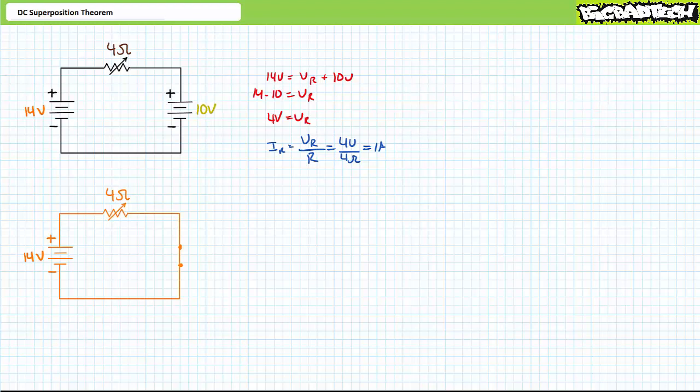Remove the deeply discharged battery from consideration by replacing it with a short. The charger would force current in the clockwise direction, and the current controlling resistor would experience the full 14-volt differential. An application of Ohm's law demonstrates current will be 3.5 amps traveling clockwise.